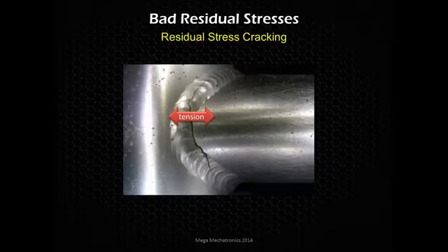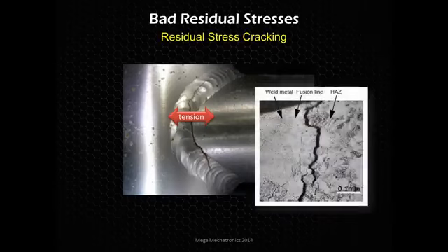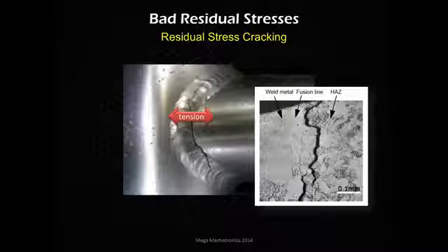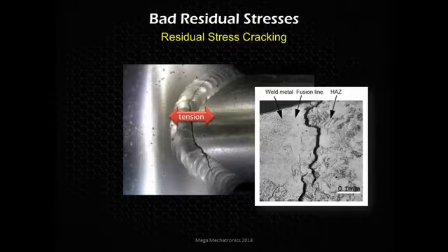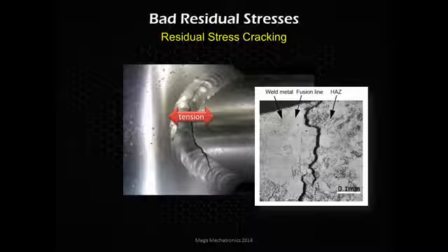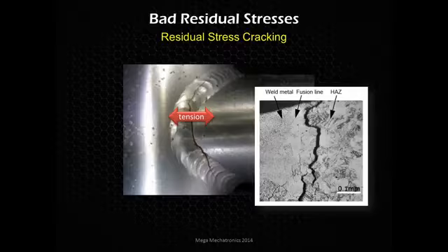So with that residual stress in there, you can imagine a tiny corrosion pit gets generated right at that fusion line, and then it just gets worse from there and cracks, where a part that was properly manufactured could be filled with corrosion, and because it doesn't have these residual stresses in there, could maintain its structure.